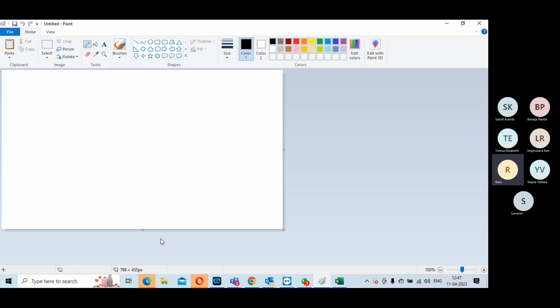They should be on proper tracks. You should ensure that the pins are connecting to the right ones externally also. If the block is abutted to this one, then those pins and these pins are to be placed exactly matching. That will come on the top. Ensure that that is done. In that case, you don't have much option to move, right?